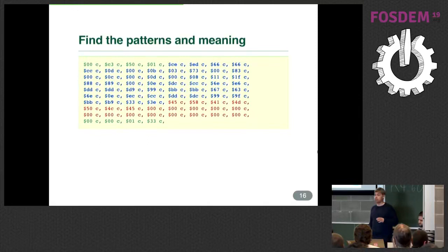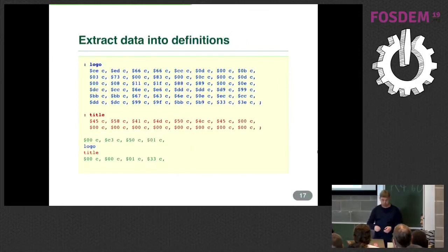Still kind of a meaningless sequence of numbers. So we went to look for offsets of where certain data is stored. The Game Boy documentation and other wikis online that we could find show a quite distinct part of the cartridge, the header, which contains some meta information like the title of the ROM, a checksum to make sure that all the bits are intact, manufacturer information, etc. And we identified the offsets of this, and we can see here I think the Nintendo logo on top, and on the bottom we have the example title for our ROM,